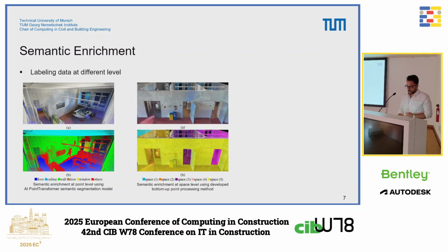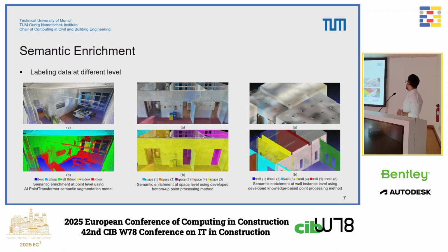And finally, for this step, we have another bottom-up approach that allows us to use principal component analysis to effectively consider the neighborhood of the points, and then individual wall instances are separated based on the orientation of the environment into three main categories of elements, let's say horizontal, vertical, and inclined groups.